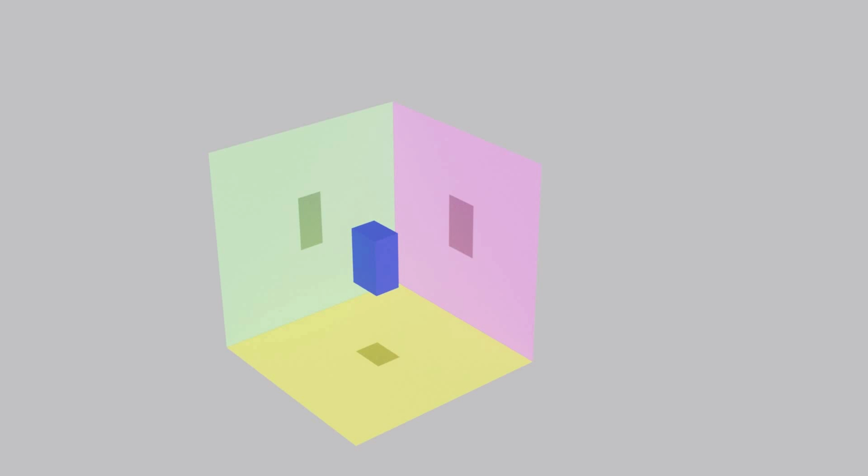This light source is kind of a laser light source. Now what is the peculiarity about laser beams? The laser beams are actually parallel to each other. They don't have a diverging nature or a converging nature. Since they don't diverge, they will be parallel to these lines. When it is parallel, it finally hits the surface and it will be perpendicular to that surface. So the projection lines from this object to the shadow will be perpendicular. That is why this kind of projection is called orthographic projection. On this surface also it is the same, and on this surface also it's the same, right? I hope you got an idea.